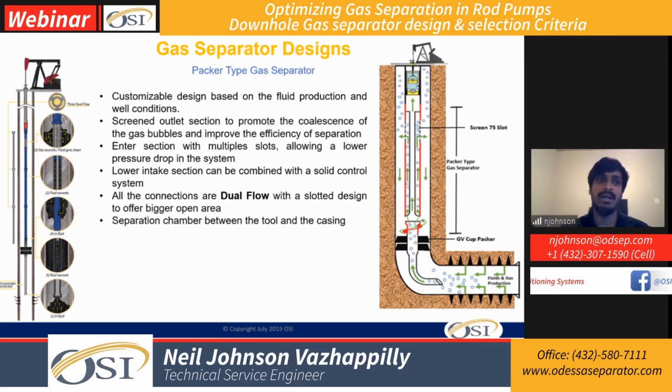So compared to a slotted outlet section, having a screen outlet section obviously helps in gas separation. Now it has its downsides as well sometimes, especially in wells with a lot of chemical issues. But we need to make sure that we can somehow incorporate a screen, make sure that it's big enough so that it works as an advantage, improving the separation efficiency.